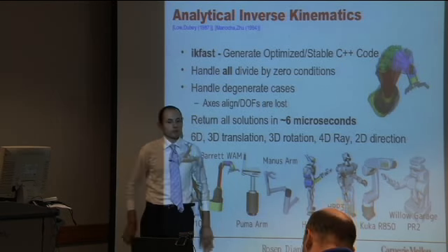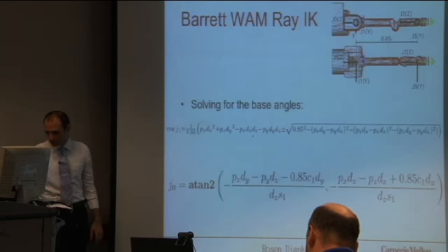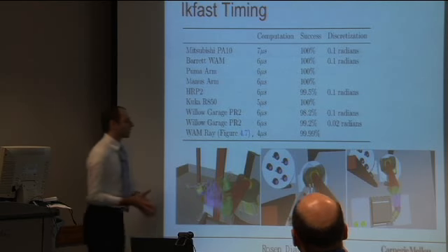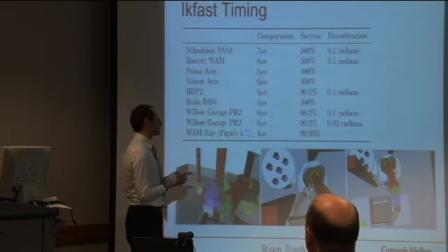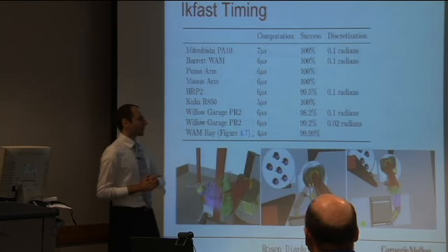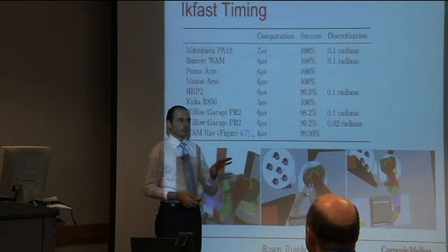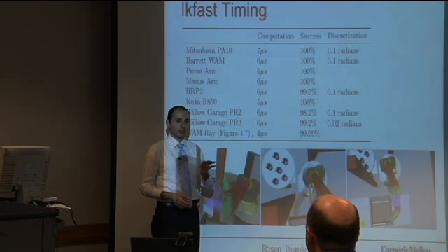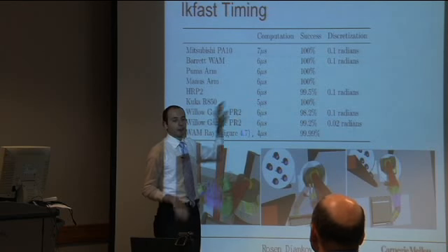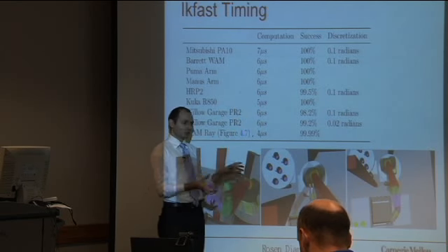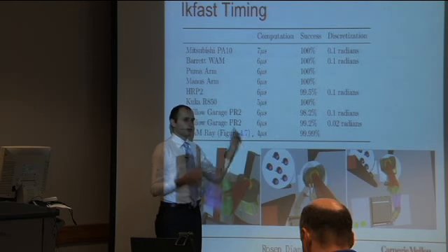On slide 31, we talk about the results. There were a couple of instances where IK-fast failed. Can you speak to why they failed, for whatever small percentage of cases? This is a really good point. What happens is, when you have 7-degree of freedom arms or more, you have to choose a subset of 6 of them to do the IK, because the IK for 6 dimensions only works with 6 joints. And you have one free parameter, which the user sets ahead of time, and then queries for a solution.